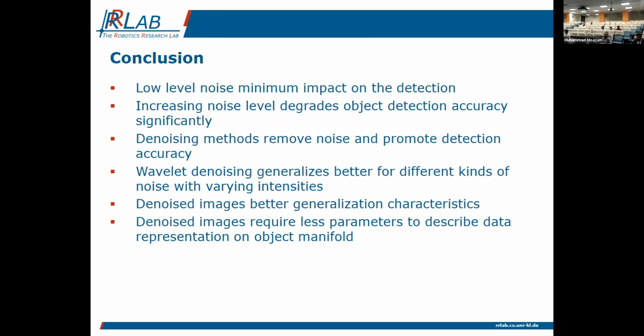So this denoising takes away a lot of that work, because otherwise we would have to cross-correlate the LiDAR with the camera view and see if this is semantically feasible, if the one shows an obstacle but the other one doesn't, and that just introduces a lot of complexity.